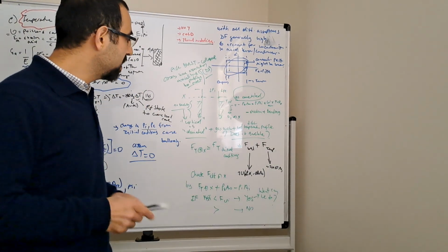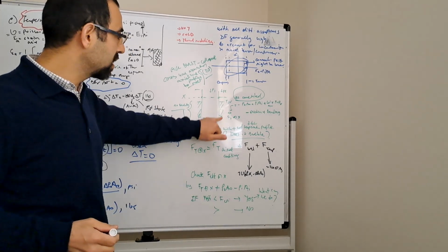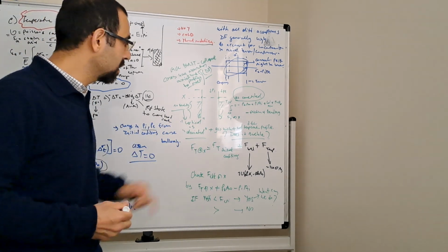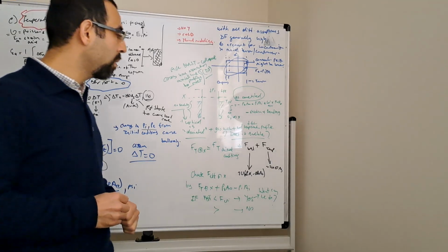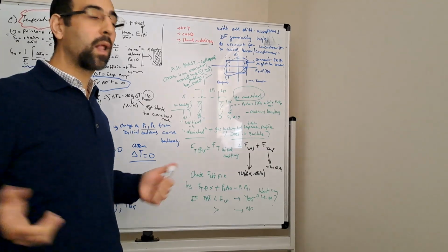And here, what we say is, for example, let's look at a case where I cemented my casing, and then I'm drilling the next hole section. So there's a next hole section here. And then I have a load case of a gas kick. I'm drilling the next hole section, and then what will be the ballooning force, or what will be the tension profile of the casing? How do we calculate it?